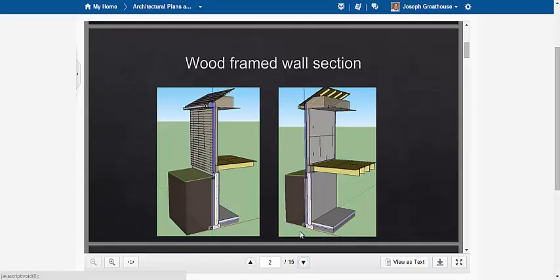Actually, we encourage that water to come in for a non-walkout basement like this one into what's called a sump pit. And you guys are familiar with the sump pump. Well, inside that pit is that pump that will pump the water out. So you guys know when you get a heavy rain, a lot of times you hear that pump turn on, and basically it's taking all the water that comes down the side of the building that ultimately collects into that tube. It's pumping that water back outside.